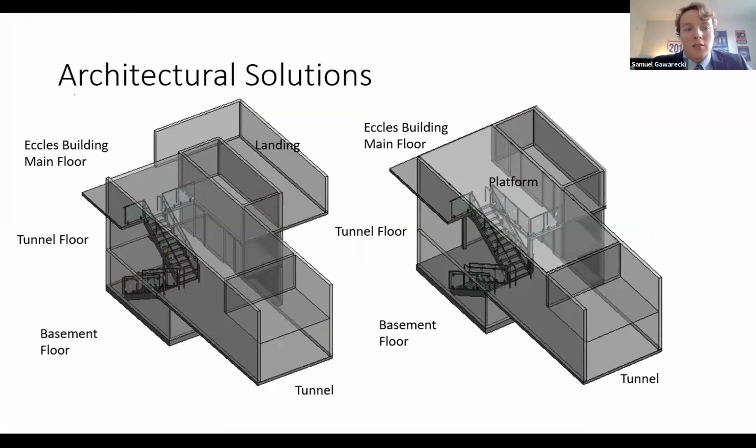From our design iterations, we decided to move forward with 2 designs for the tunnel connection. Both designs include a scissor staircase and 2 elevators, allowing for easy access and movement between the 3 floors. Again, for both designs, the elevators need to be put into the wall, so whatever is behind it will need to be relocated. We were sure that this would be acceptable by the Federal Reserve.